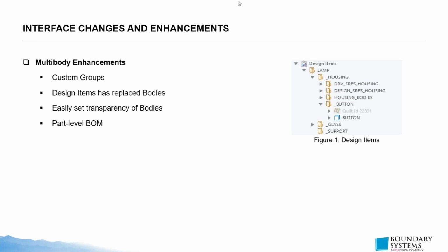Additionally, we're now able to easily edit the transparency of bodies. So this can now be done in the quick access toolbar with just a single click. We can edit transparency and also through an additional menu in the InGraphics toolbar, we're able to adjust what that default transparency value is. So I'll show you all how to do that in just a second.